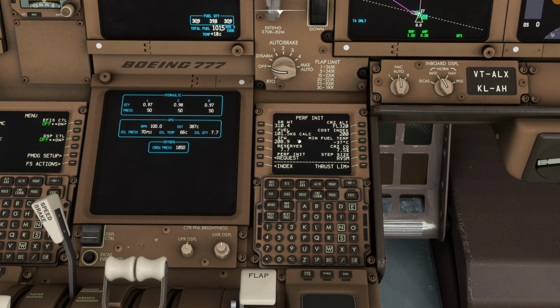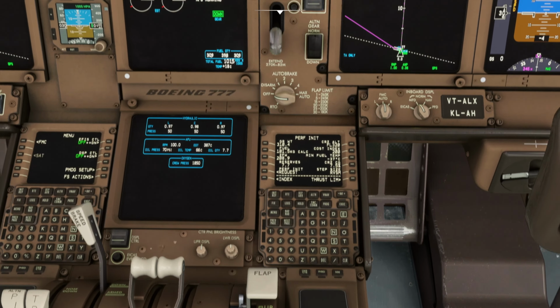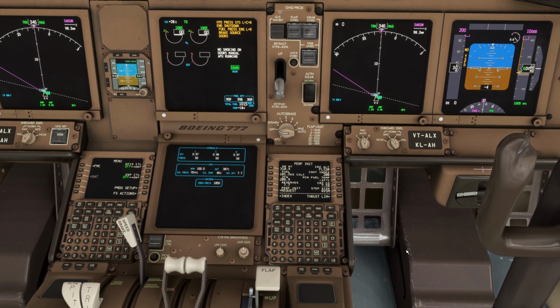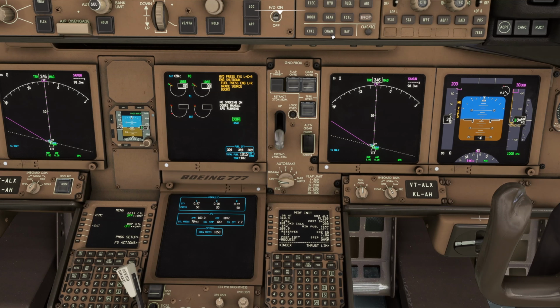And this is actually not the correct time to put the zero fuel weight. In the actual airplane, you fill it in when you get the load and trim sheet, either a manual load and trim sheet or via the company, on company messages here on COM. On company messages you get the load and trim sheet here, so you can verify and check from here.